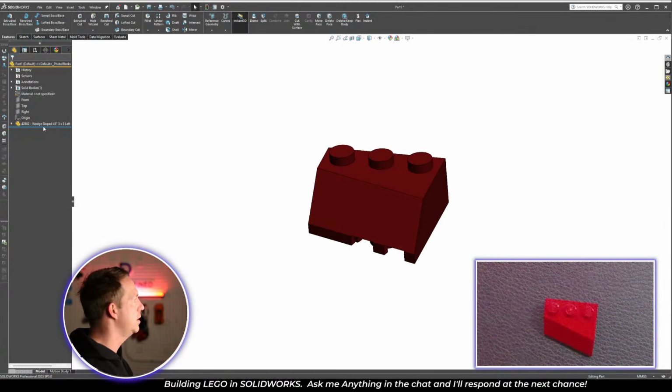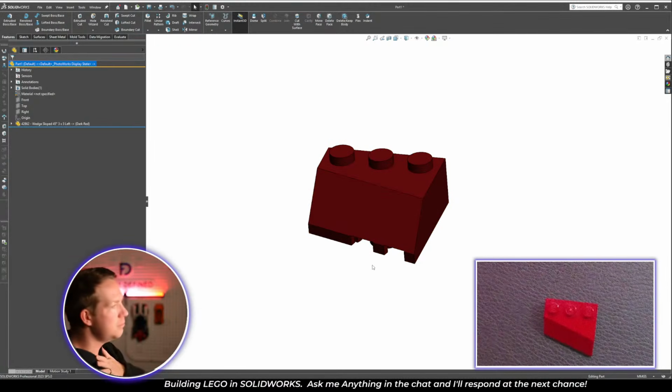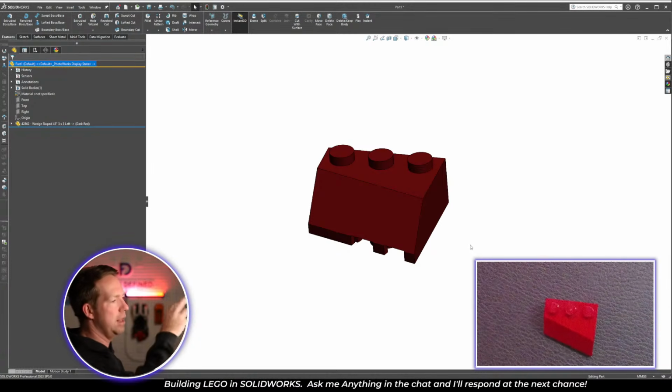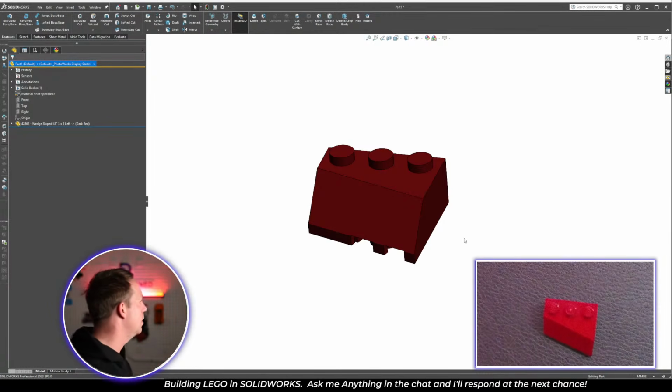And it brings in my part file, and you can see it here. And this links to the original. So if I made changes to the original, that'll then show up in this file. And so if you have a master part, you do those details, you break it up into all the child components, and then it'll show you bit by bit where those features are. I do have a couple of longer videos on the channel that show you some of that information, so check them out.